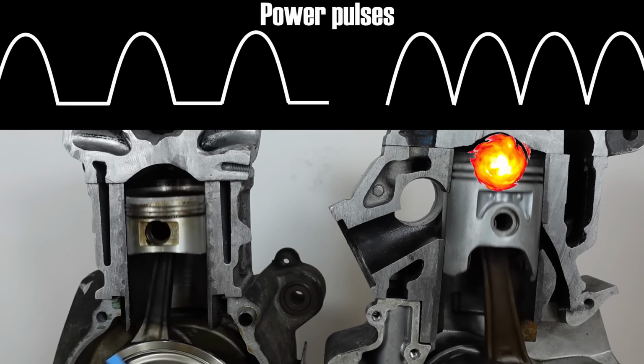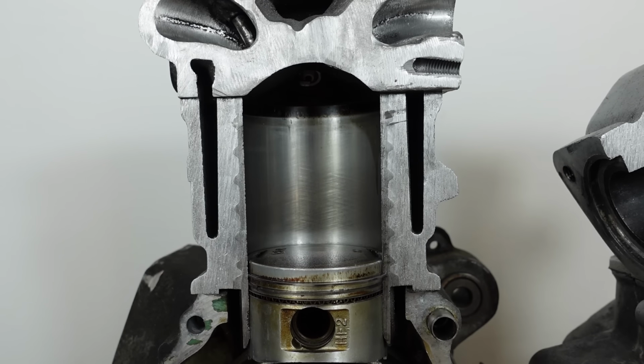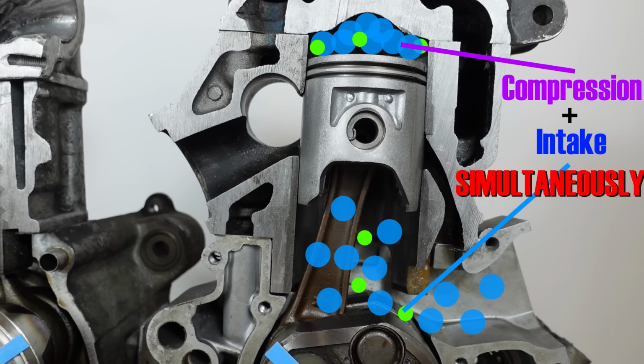The other important thing to note is that the strokes are very clearly defined and separated in a four-stroke engine. Each completed stroke of the piston marks the beginning of one and the end of another stroke of the combustion cycle. But the two-stroke engine sort of lumps the strokes together. They overlap and occur simultaneously. The two-stroke is actually multitasking, which enables it to squeeze more action into the same time frame. But as with everything, there is a price to be paid.